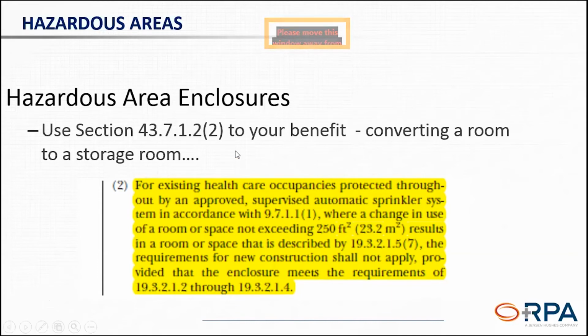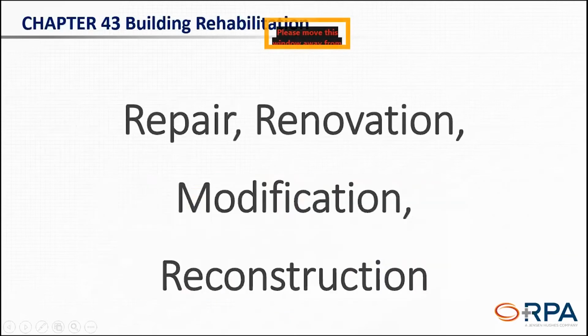So you can see we can use this section to our benefit if you're trying to take a room at the end of the hallway or a vacated space and turn it into a storage room. As long as it's 250 square feet or less, then we can do that with the proper protection. Going into chapter 43 a little bit more, repair, renovation, modification.